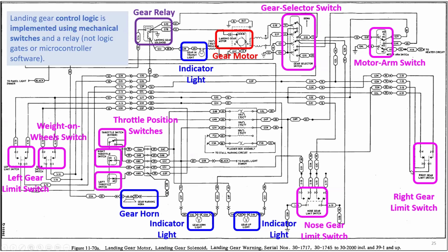So the gear switches, the limit switches, the pilot actuated switches, they all make the control work with this wiring, and not a single semiconductor in here. So it's pretty interesting to look at this. Okay, so got to give some respect to the mechanical switch for getting this whole system to work. But I mentioned a relay here, so let's talk about relays.